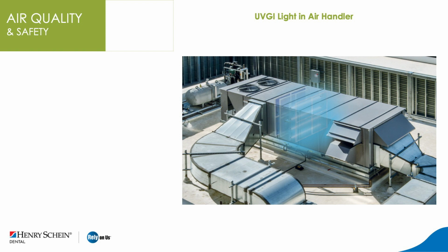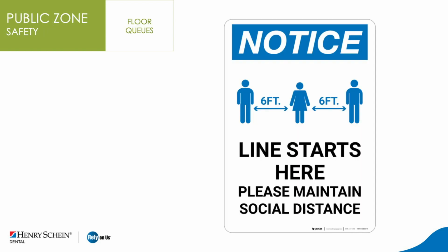That's the current recommendation. But here's the caveat: most built-in humidifiers are not common in commercial systems because of mold considerations. So maybe a much more effective way of handling this is to use portable room humidifiers placed strategically throughout the office. And that's going to really help with the overall management of humidity in the office.